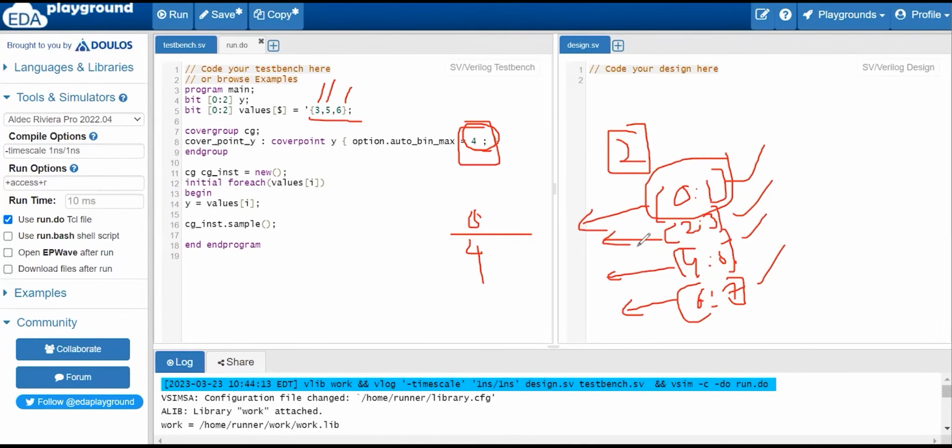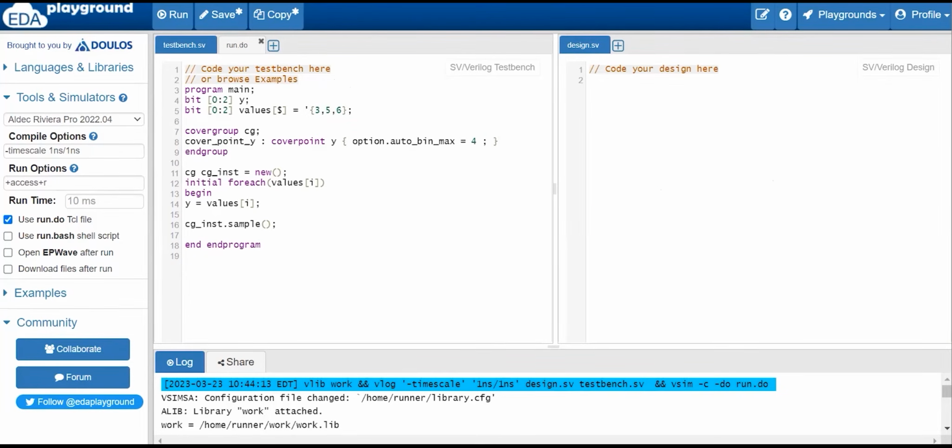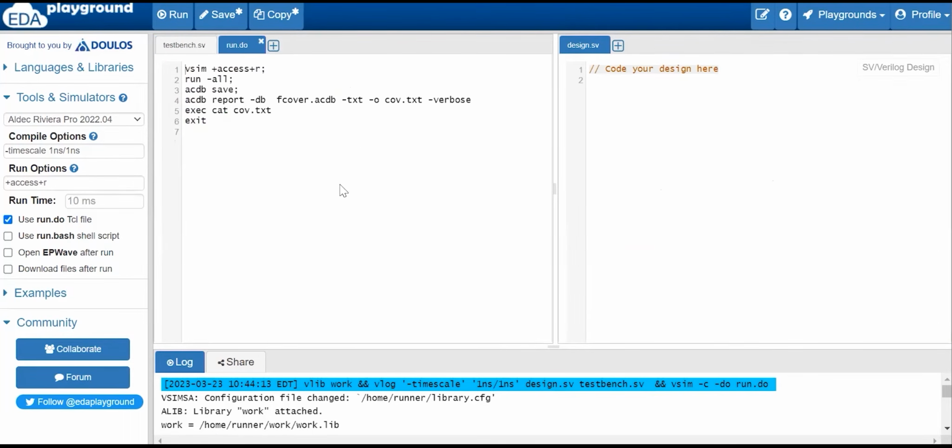If you see at SoC level or IP level, this particular bin is not covered. So we'll check the coverage report now. How will we understand? Here we are just telling it theoretically, but we'll see how the coverage report is generated. See here, run.do options. These are the options here to generate the coverage report. These can be found on Google. In Google it will also be available, you can check there, otherwise I will share it with you. Okay, so I'm doing run.